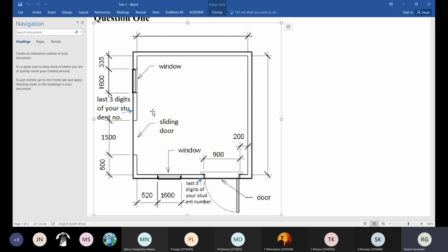So that gives me another 12.8 plus 19.2. That came to exactly 32 meters of brick force that I would have had to minus from the total. Okay, and that's how you would have calculated the total brick force for there. There are no internal walls. Only one.